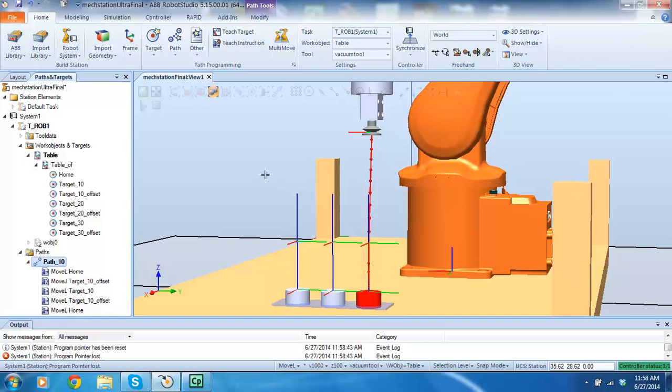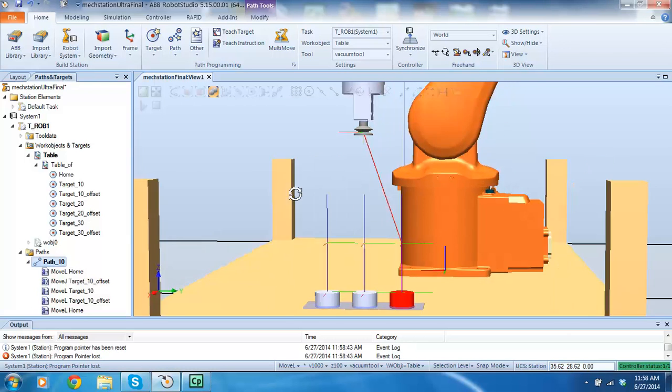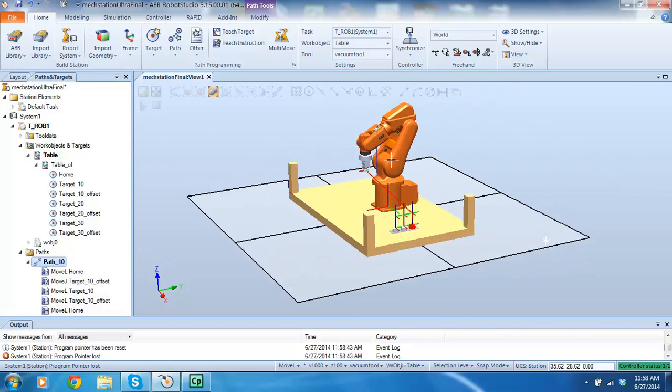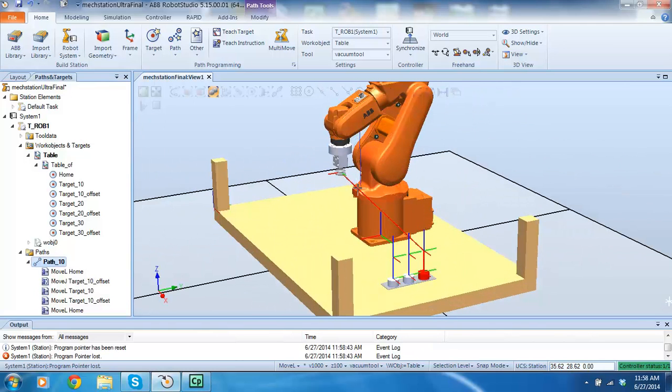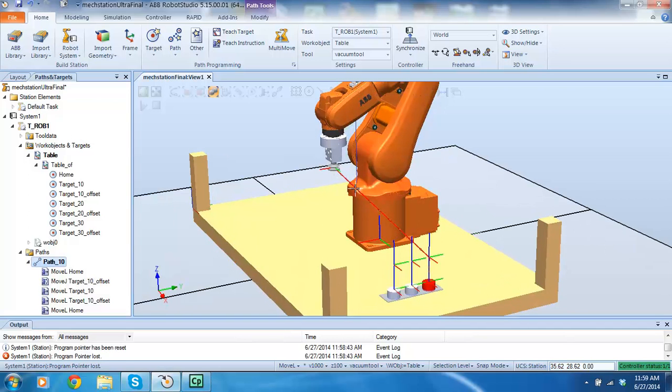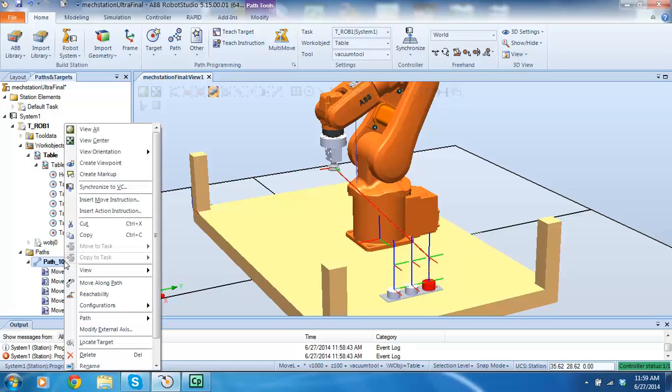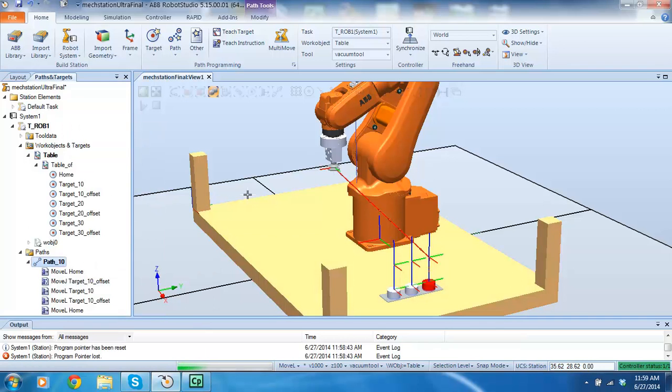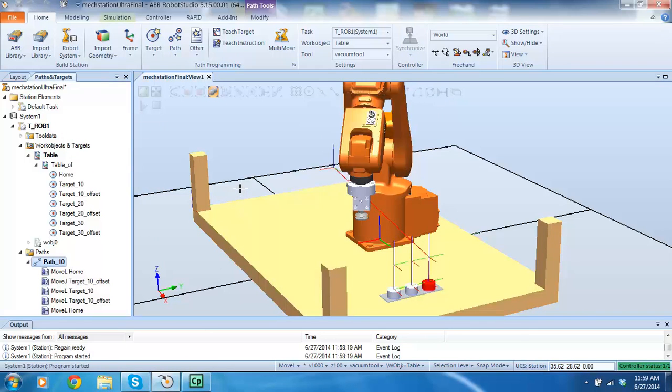And it's actually less work for the robot. All you're saying is you start there, and anyway the robot can get to this point, you do it. And what it will do is just do the minimum amount of movement. It doesn't have to calculate each of these points. Whenever you have a move L, it needs to know where all of those points are. A move J command is saying, look, that's your start and that's your end point. You get there whichever way you want, the quickest way, so it'll just bend around it. Let's run it again and look at it. Notice that it doesn't follow the line.